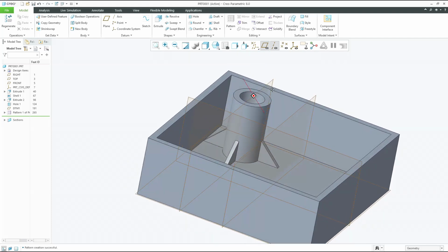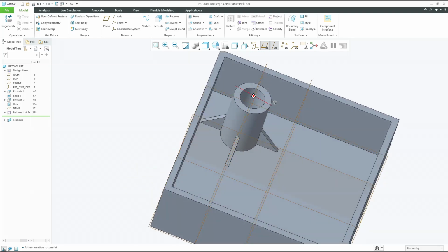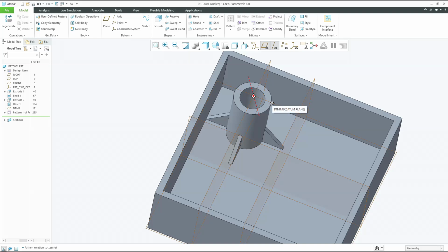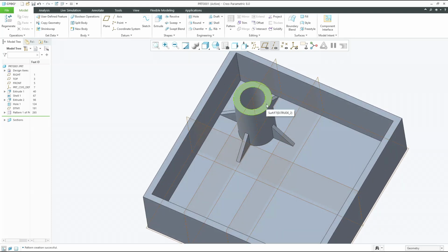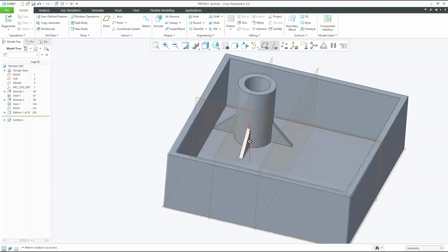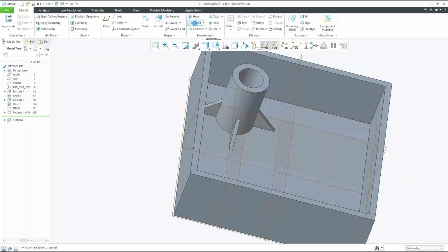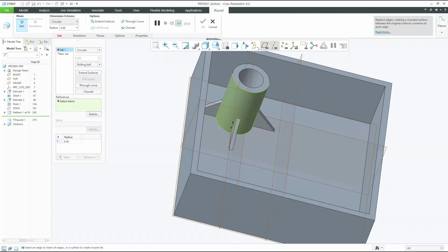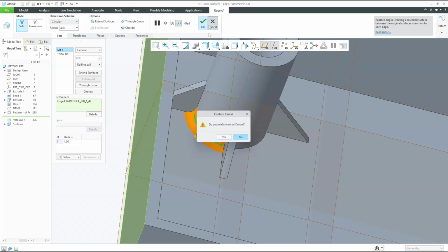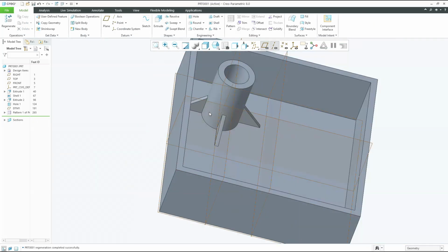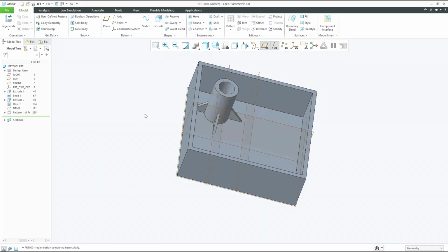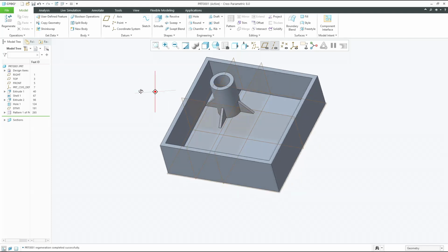So now you can ensure that the strength of the cylindrical boss has been increased with the help of the profile rib. So whatever the load or the torque you're giving along with your fasteners, there won't be any damage in this. Even if you're making it in a casting or injection molding, please make sure that you have used proper round fillets in all the corners, so that it may reduce the stress concentration at the sharp corners. So this is how the profile rib has been created.